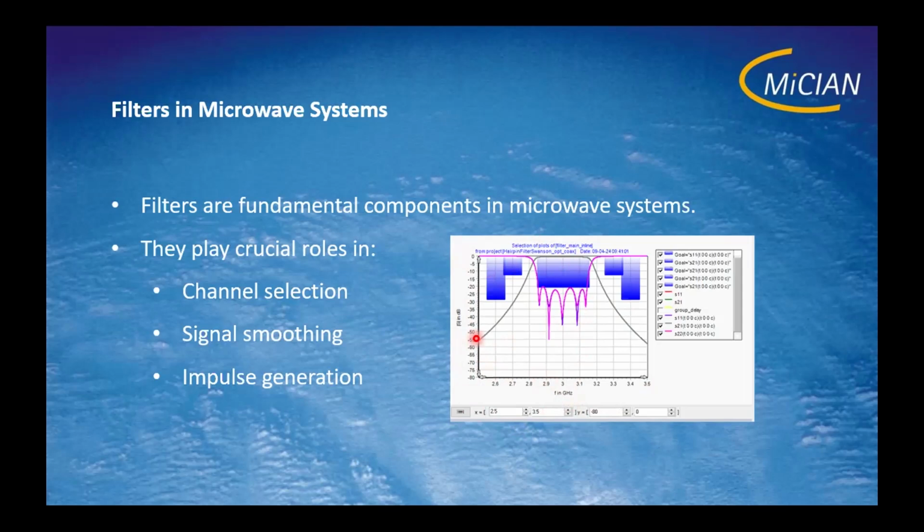So this is the response of S parameters against frequency. The gray line is the S21 response, and the return loss is given by this purple line with poles and zeros, which is S11.